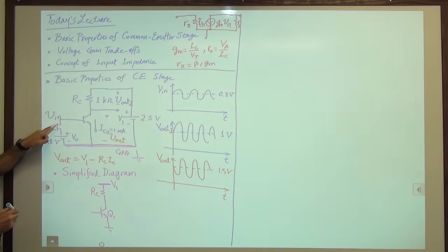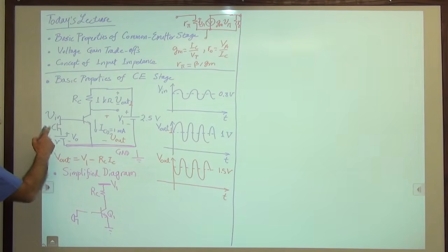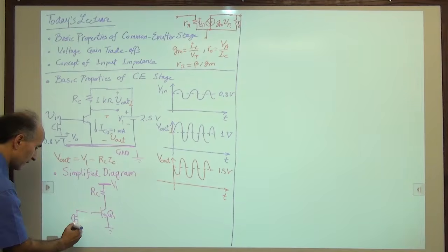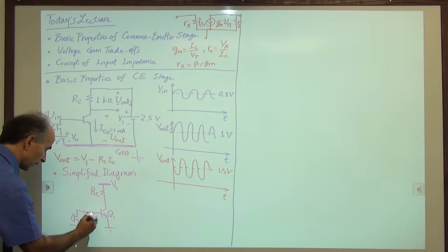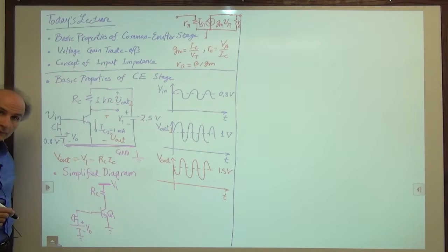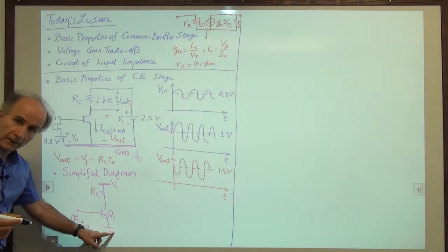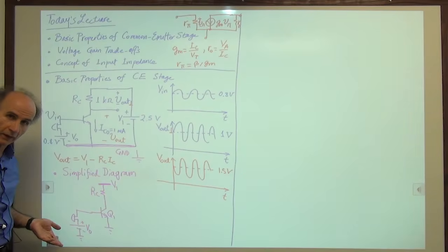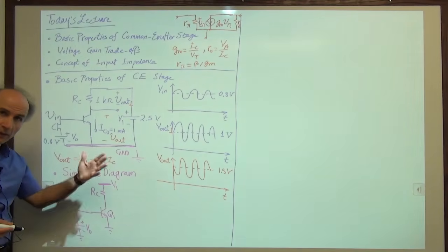I have this voltage source and this battery going to ground, so I draw, for example, the microphone or a representation of this voltage source and the battery going to ground, and this is V0, and that's the microphone. So this should not be strange or confusing. All this means is that these are just connected to each other by a wire. That's all. We just don't want to draw the wire because it clutters up the circuit diagram.